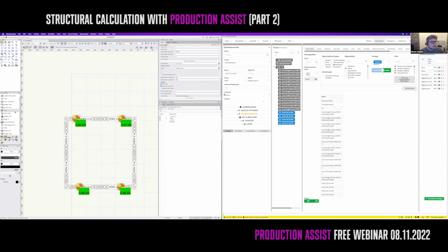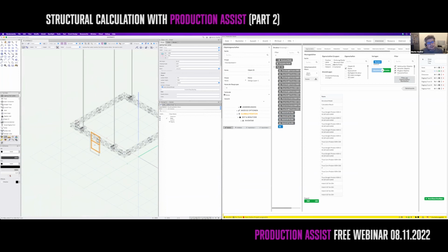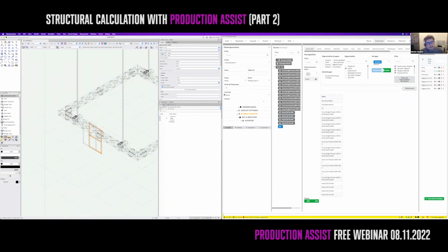The next thing that we want to do is our lightning pipe ladders. There's a specific tool for this, called lightning pipe ladder, and it allows me to insert a lightning pipe. The lightning pipe is a really cool tool in order to generate such lightning ladders. You can define the height, for example, 5,000, and you can define the ladder width, for example, 1,000, or, well, let's do 500. And you can define the number of rungs. Let's use 8. So now what we have in here is this specific lightning pipe ladder.